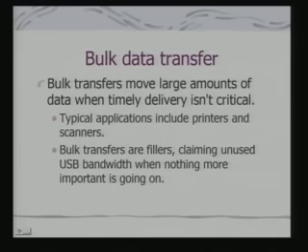In many cases bulk transfers become fillers, claiming unused USB bandwidth when nothing more important is going on. Since there is no deadline to satisfy, it is not essential that the USB bus has to make a guaranteed bandwidth available to this transfer type. So, it can be put in whenever there is a gap, but a large volume of data is to be transferred. This is the basic aim.